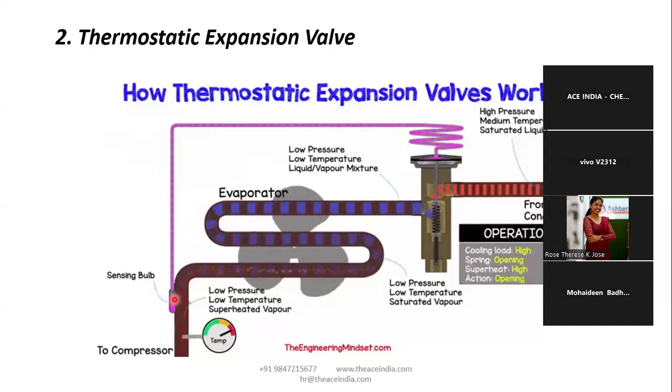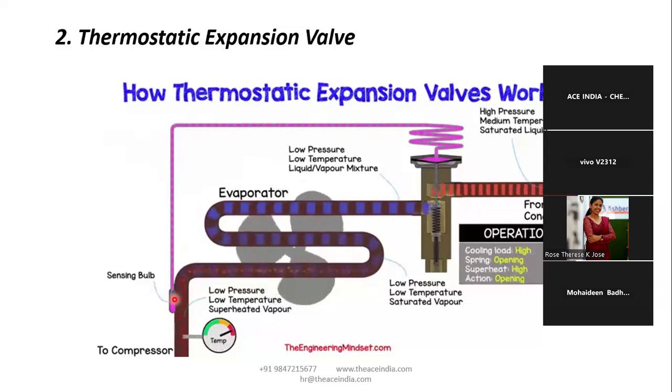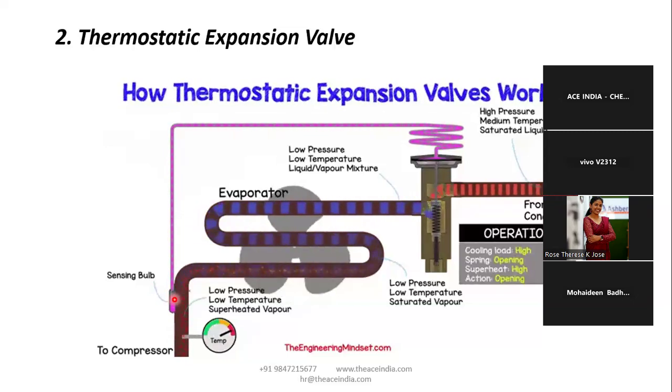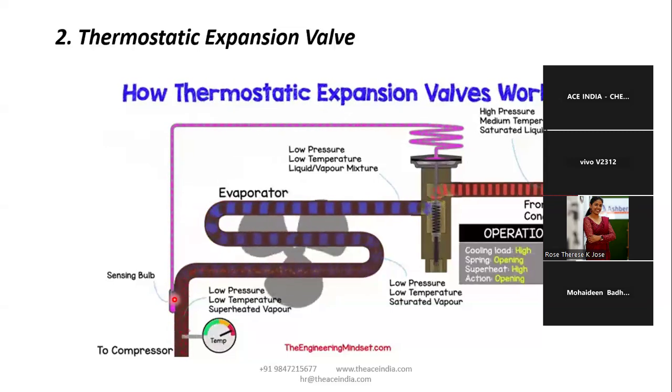Okay, so here, if the temperature exceeds a certain point that is preset on that specific electronic expansion valve, a small opening and closing will happen according to some kind of feedback. So in the case of an electronic expansion valve, you can see some small motors like a stepper motor, and some kind of magnets will be there. The working is very simple.